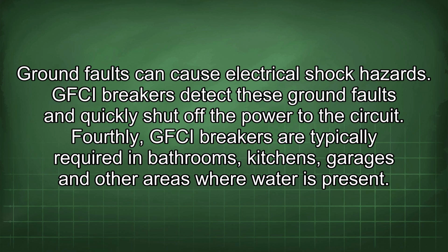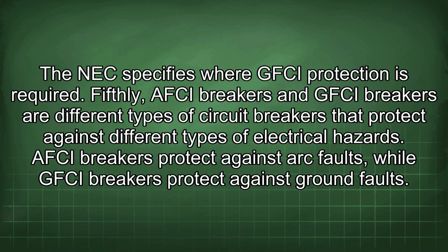Fourthly, GFCI breakers are typically required in bathrooms, kitchens, garages, and other areas where water is present. The NEC specifies where GFCI protection is required. Fifthly, AFCI breakers and GFCI breakers are different types of circuit breakers that protect against different types of electrical hazards. AFCI breakers protect against arc faults, while GFCI breakers protect against ground faults.